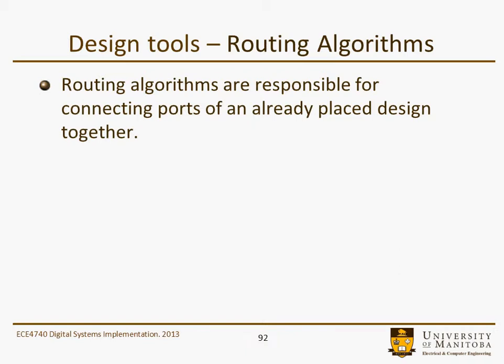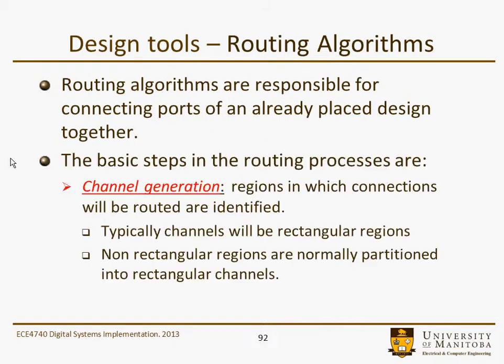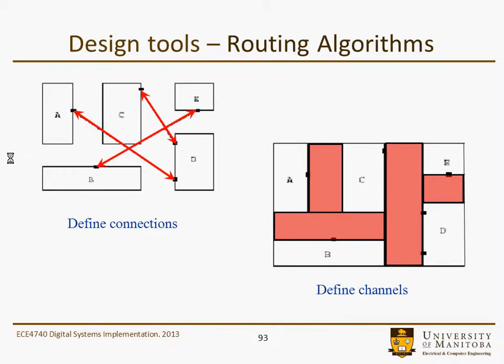So continuing with some design tools, we're looking here at routing algorithms. Routing algorithms are responsible for connecting the ports or the I/O of an already placed design together. It's usually accomplished in several phases. One phase will be the channel generation, so you have to define regions in which the connections will be routed. Typically the channels are rectangular regions, and non-rectangular regions often are partitioned into rectangular regions.